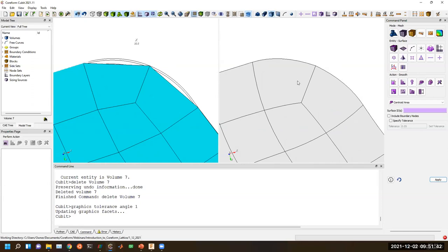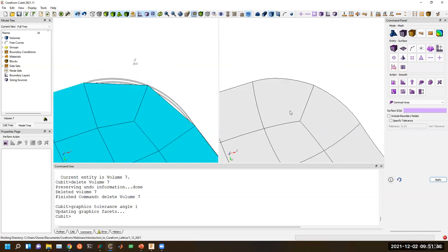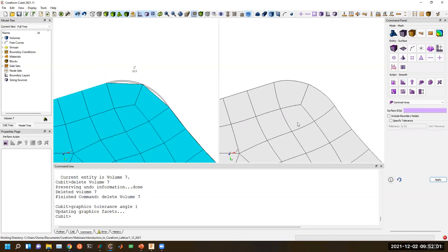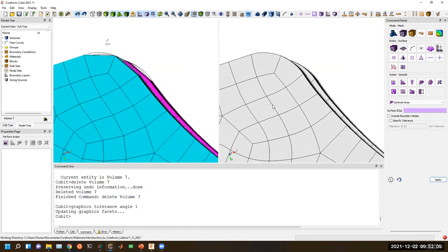Right now we use a technique called Bezier projection with our U-splines. We aren't building rational U-splines yet, and so these are technically just an approximation to the original CAD geometry because they're polynomial as opposed to rational, for these cylindrical faces. We are working on rational U-splines as well. But they are a better fit.